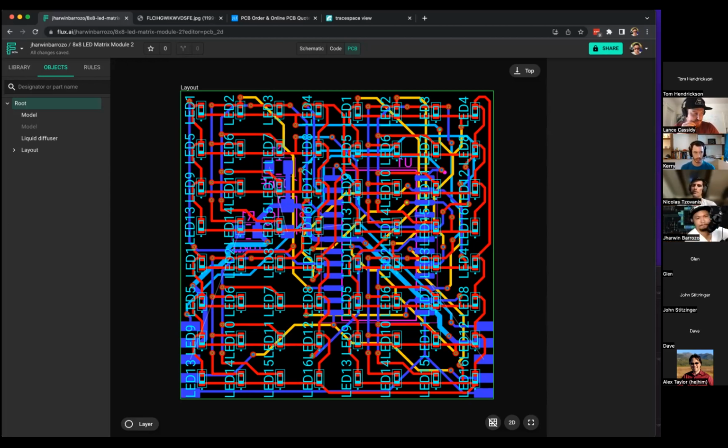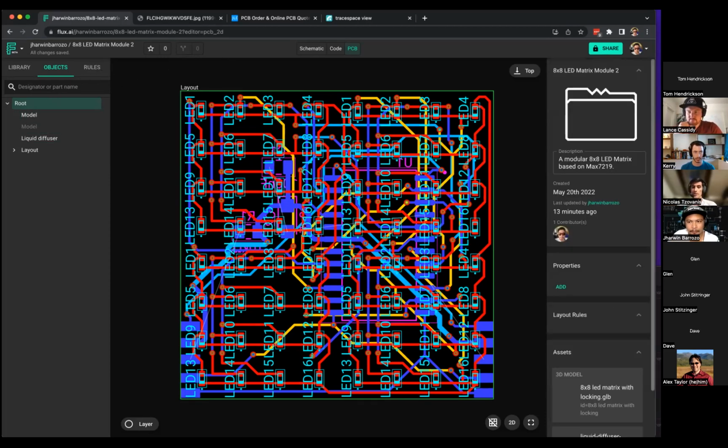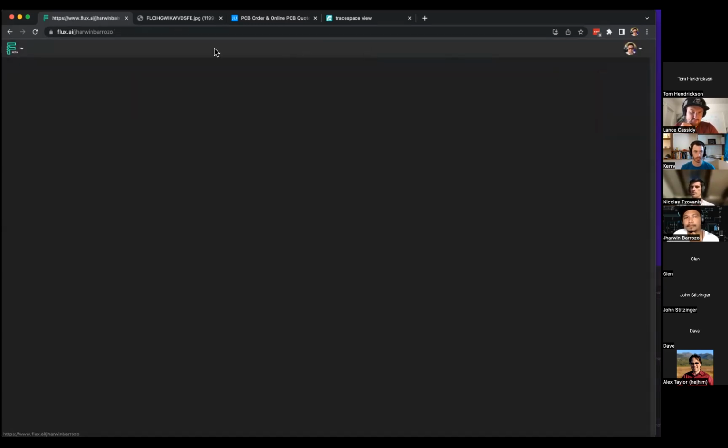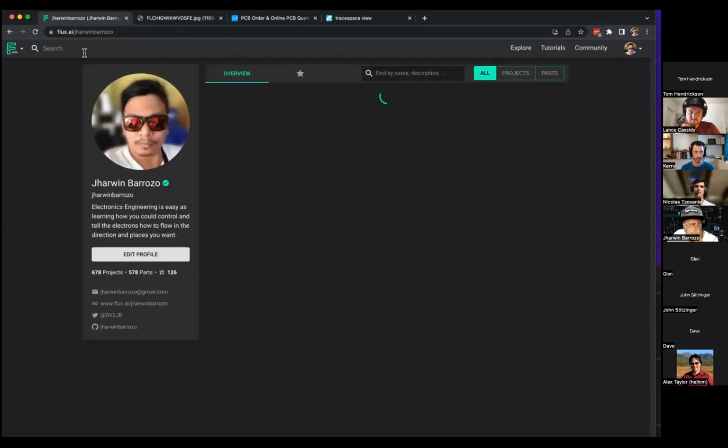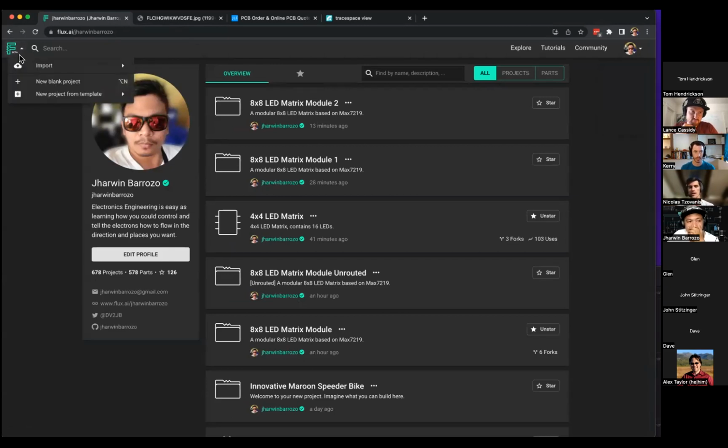We have many of them that are done live. For example, the track width and all that, the tool won't let you mess those up. If you set up a minimum trace width, the tool won't let you put anything less than that minimum. So some of those won't make sense or won't be needed. But some others, like no unrouted nets or things like that, we'll provide when we implement the DRC.